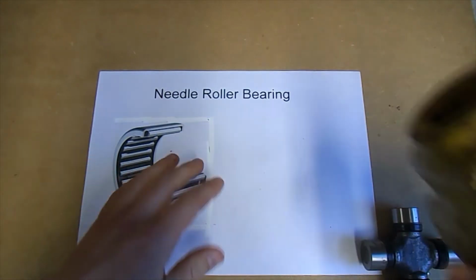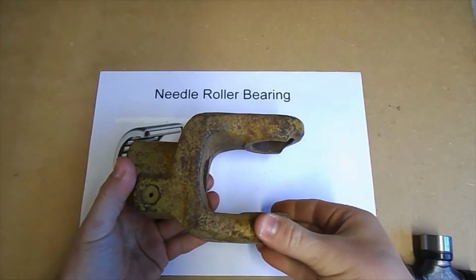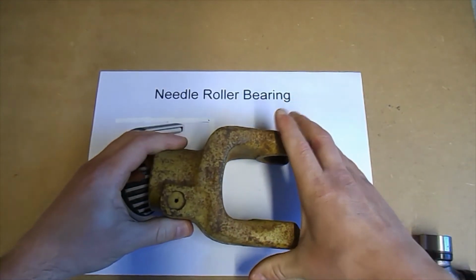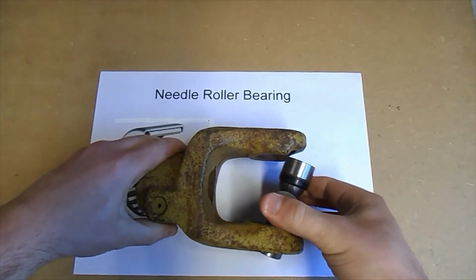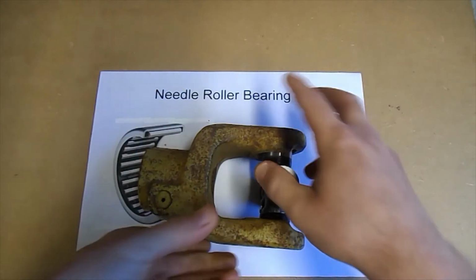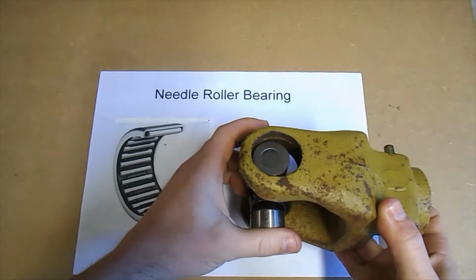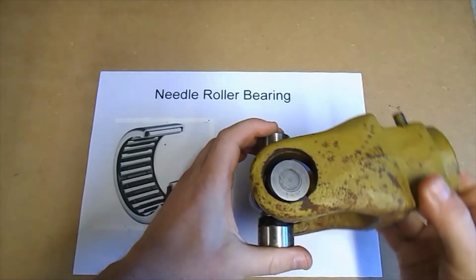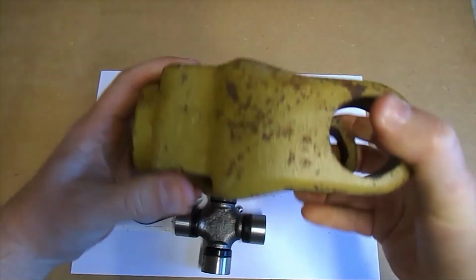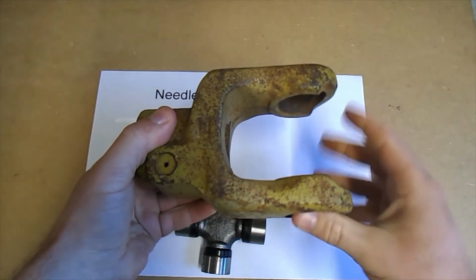So this works by using 2 yokes opposing each other. One will be in this orientation, one like that. So this one would sit there. Universal joint would sit inside, allowing the yoke to move up and down. And the opposite would allow this yoke to move left and right. So you can see that as this yoke is spinning, it allows your shaft to move in whatever direction is required.